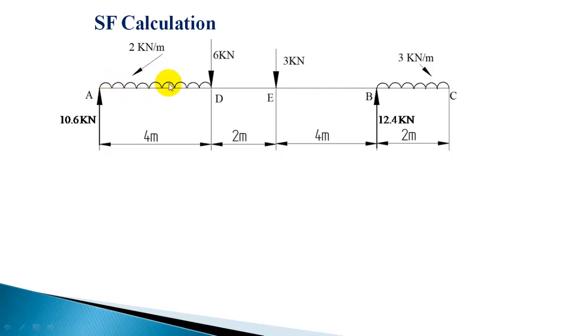So wherever UDL or UVL comes, you have to find out the shear force on either end, not exactly at the end, but an infinitesimally small distance away from the end in the UDL part or UVL part. You should calculate the shear.